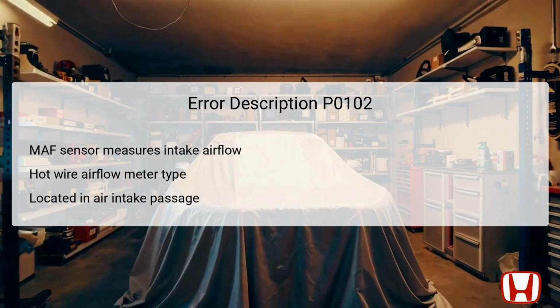The mass airflow MAF sensor is designed to measure the volume of air entering the engine's intake. It operates as a hot wire airflow meter. This means it uses a wire that is kept heated, and as outside air flows over it, the wire cools. The signal sent to the powertrain control module, PCM, is based on how much current is required to keep the wire at a set temperature. This current reflects the rate of airflow.